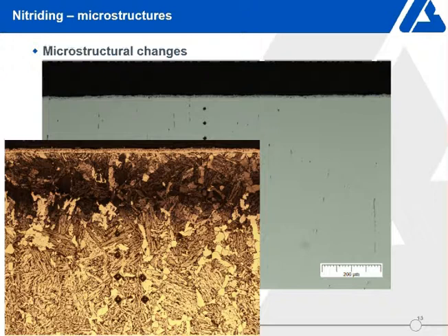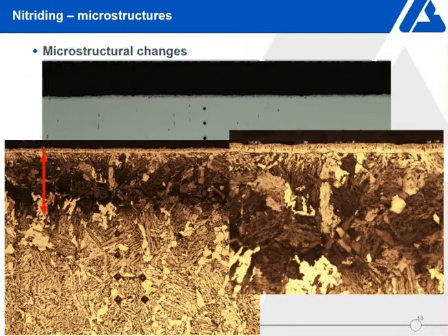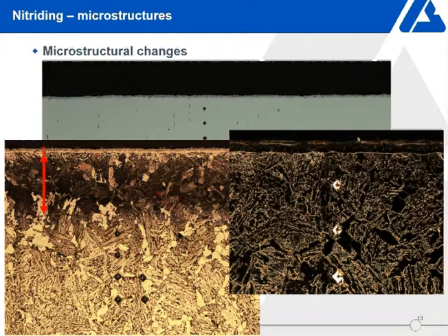So there are impressions there that might not be readily visible. And this is just a blow-up image, again, to show you the white layer and the respective microstructure in as etched situation. We've also just included a dark field image to illustrate where the impressions are. And this is why I was mentioning before, sometimes for these kind of surfaces, you may need to do the testing before etching, because most of the time, hardness testing does use a contrast technique to accurately measure your impression.